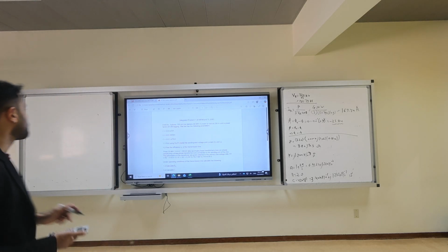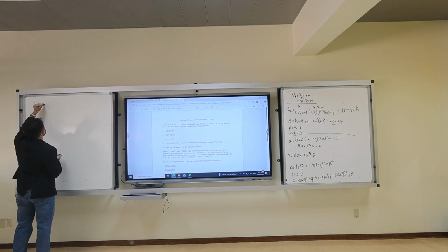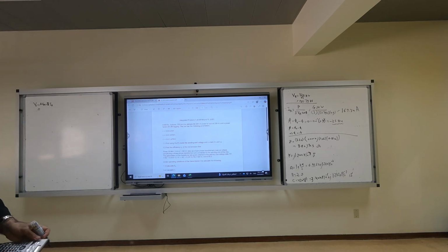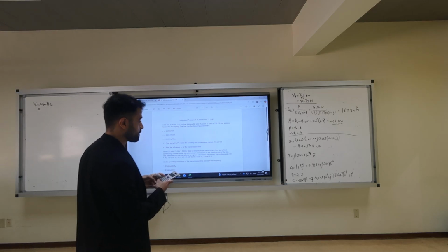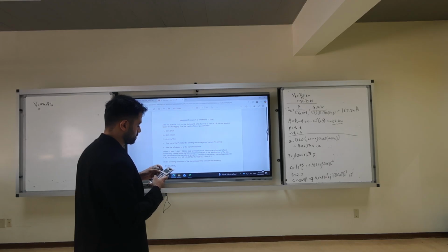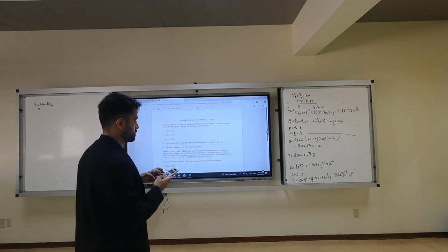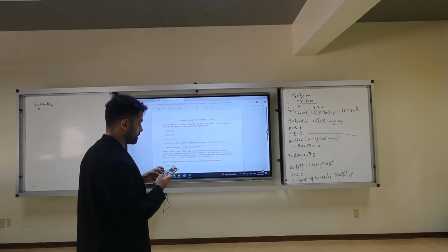So, what is Vs? Vs is A VR plus B IR. What is A? 0.9569 plus J times 5.360 times 10 to minus 3 times 132.79, plus IR times B, 8.8 plus 70.5 J times IR, which is 167.34, angle minus 25.84.